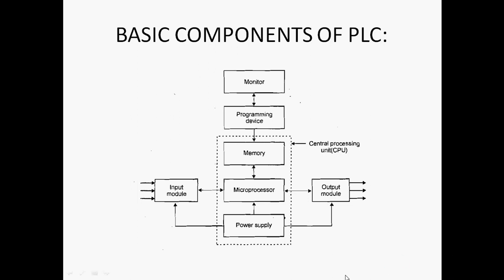So input modules we require for the sensors. Then different types of switches we are using for the input module for giving the inputs to the system for processing for the output module. So in between there is a memory, microprocessor and power supply. So power supply is required for input, output as well as the microprocessor. So this relates with the basic components of the PLC.